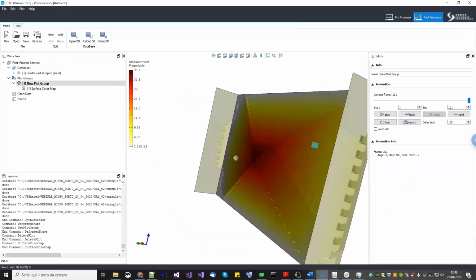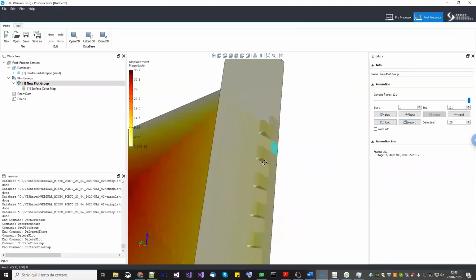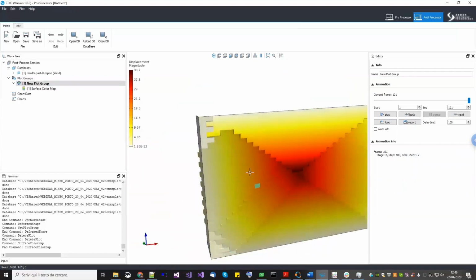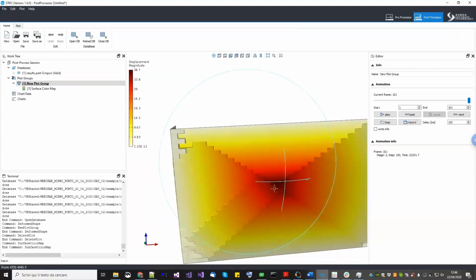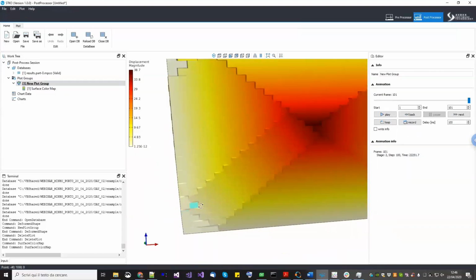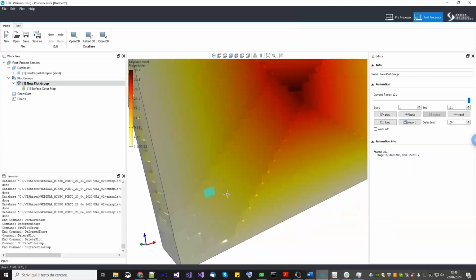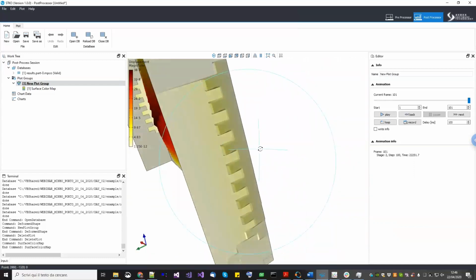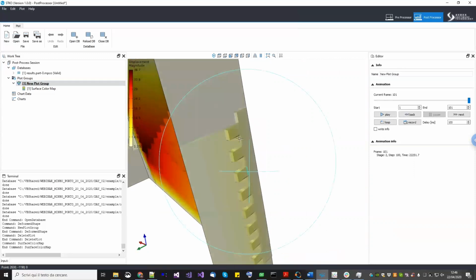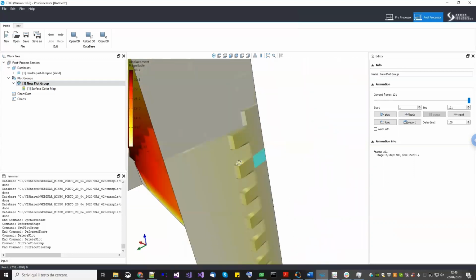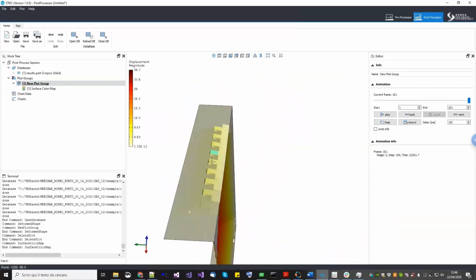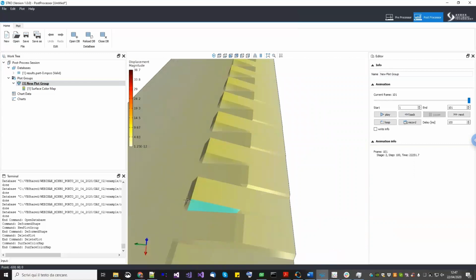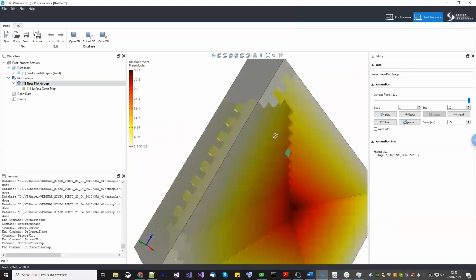And the nice thing about this kind of shell element is that if you have a look, you probably would expect a bending failure. This is an overall bending failure, but actually what is failing is the out of plane shear. That's why at the beginning I told you, look, if we use the thick shell, the results will be fine, like this one, because even if the overall failure here is a bending failure, what is actually failing is the shear failure of these mortar joints, same as in this case.